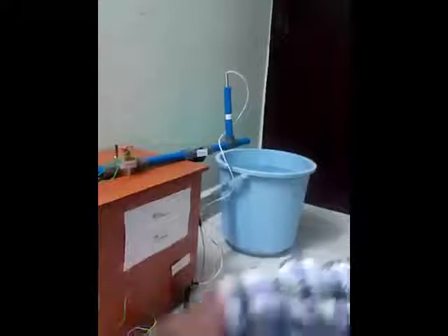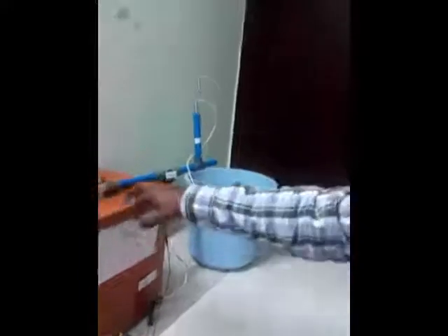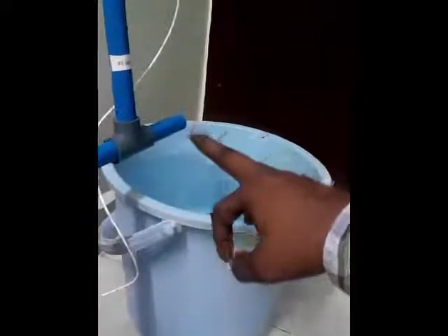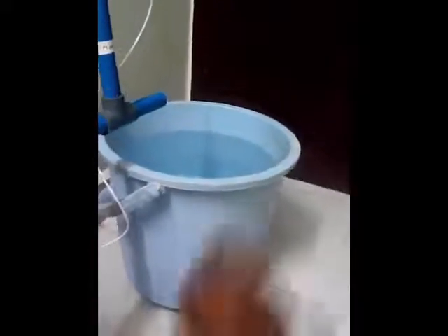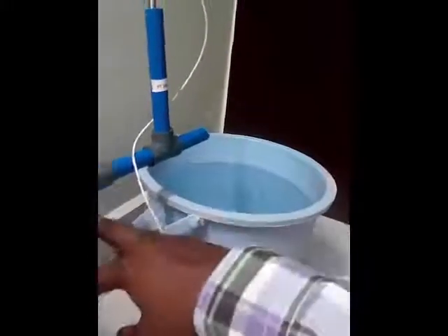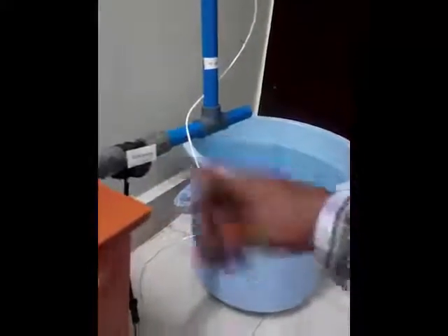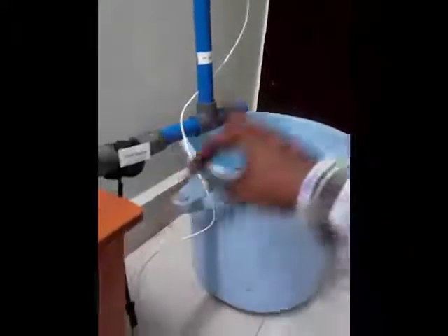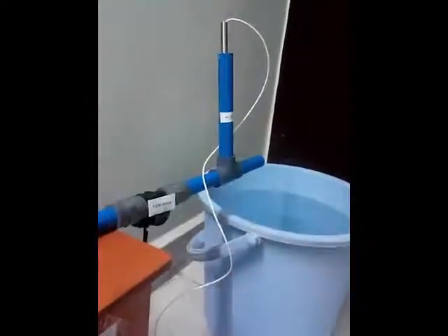If you see this system here, we have seen the sensor 1, sensor 2, sensor 3 values. Now the hard-coded value that we gave has been reached. So the solenoid valve switches off, and the flow sensor and PT100 values are just displayed in the XCTU. If you see the outlet, only a few droplets are there. That is because the flow sensor will not switch off immediately, so it takes some time for the remaining liquid to flow out. The flow sensor and PT100 values will send out this data.